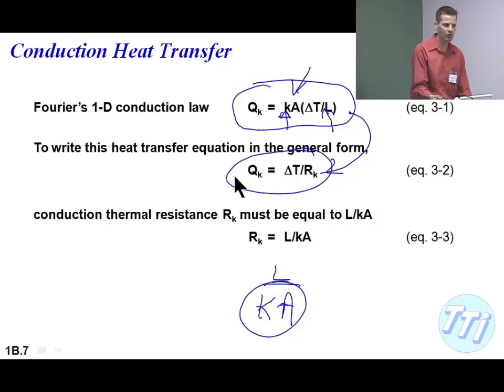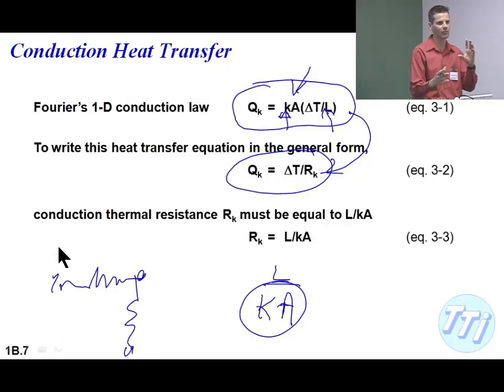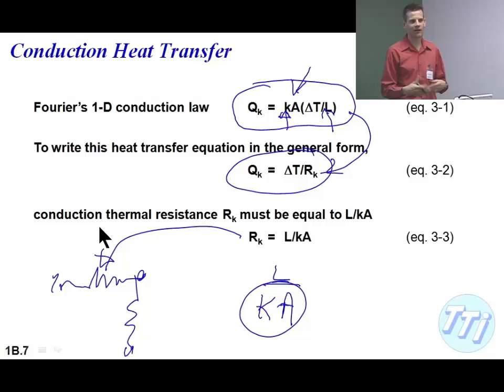If you're not familiar with them, we'll talk later about building nodal networks, which look like electrical diagrams where you construct a series of thermal resistors between parts in your system. You can dump these resistances into these nodal networks and quickly do a hand calculation at your desk to come up with a concept for a thermal design. I do this all the time, and it's a real effective technique.